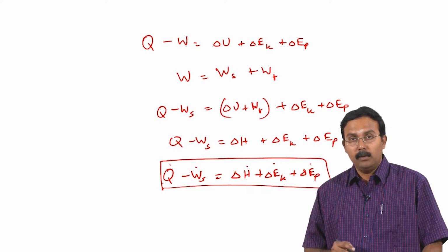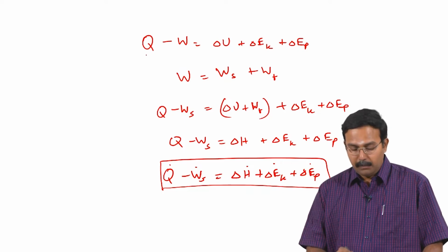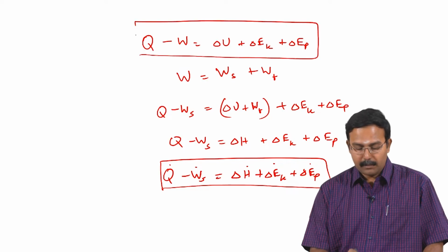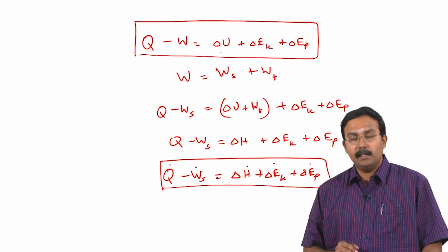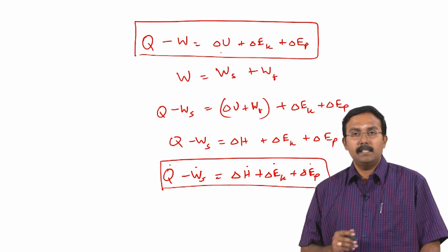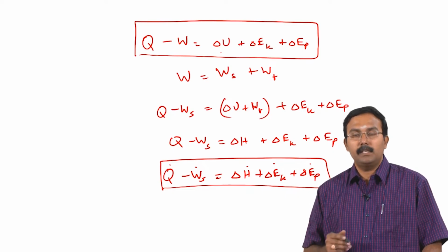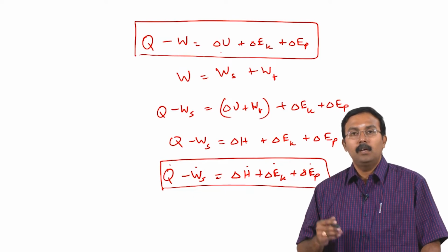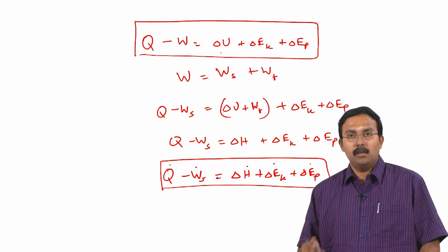However, today we will be looking at a closed system, so we will be using this equation, where you use specific internal energy instead of specific enthalpy and then finally calculate the change in internal energy to understand how much heat is required. This is applicable for closed systems at constant volume.